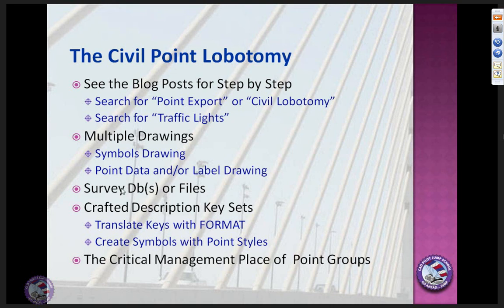Using a crafted survey DB file, right? Survey database or point files. We could have used either, but a survey DB has that wonderful in-out capability. So I usually say, hey, make yourself a survey DB. You can make it literally from a drawing, right? Open a database, pull the points out of a drawing and stick them in a database. Really? Yes. Okay, and put them back in as you need them.